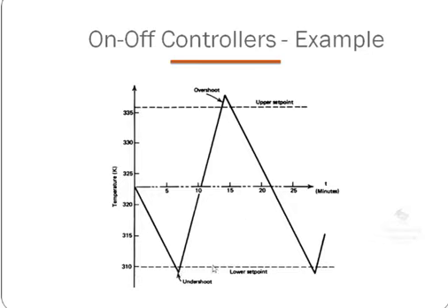Again, my controller will give control action to the heater. You switch on the heat. So what will happen? It will start to increase the temperature. So it is slowly increasing. And whenever it is crossing the upper set point, which means it is crossing the neutral zone value, what will happen? It has to reduce the temperature, because my ultimate aim is to maintain within 320, exactly